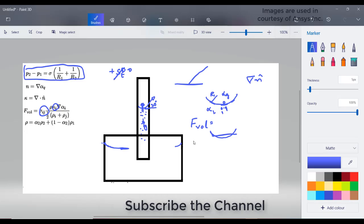Rho is the combined density, which at the curvature is alpha 2 rho 2 plus (1 minus alpha 2) rho 1. So it is a mixed density present near this curvature, and rho i and rho j are the densities of either of the fluids, right? This is the net force that would be generated, and this force is replicating this formula only. The entire term signifies the radius vectors.